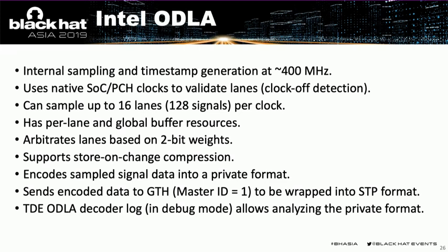The on-die logic analyzer supports store-on-change compression, which greatly reduces traffic between the trace hub and the selected hardware interface.